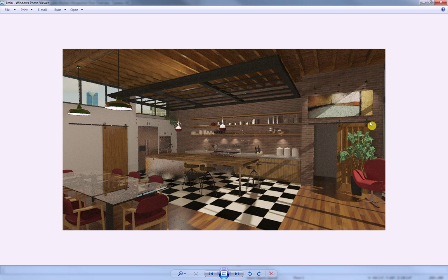And you can choose to stop the ray trace at any point in time, or you could specify an amount of time or amount of samples that you'd like to do, if you know typically how many samples you like in terms of the quality. So here's after 1 minute. I'm going to run through some slides. The next slide that you see here is after 5 minutes of ray tracing. So you can see a big improvement in terms of the quality, and this does include photon mapping in this ray trace.